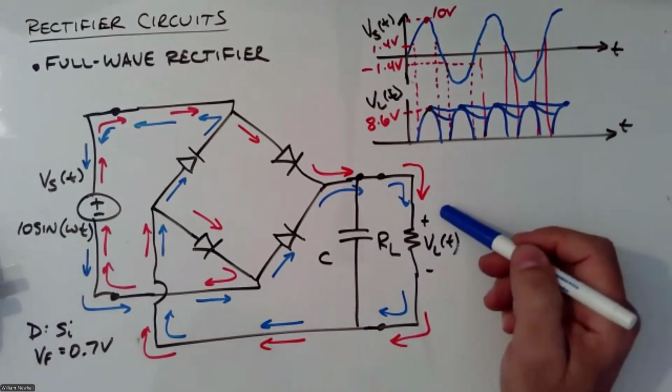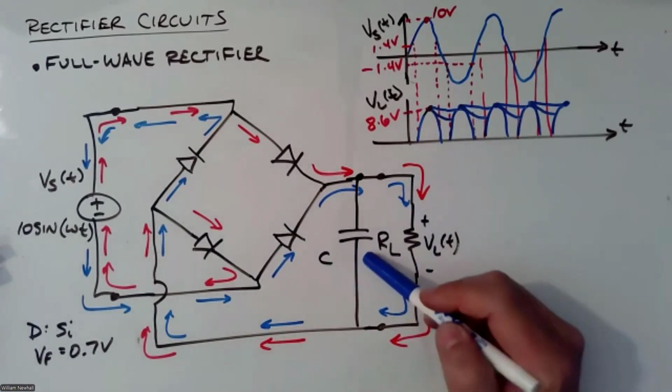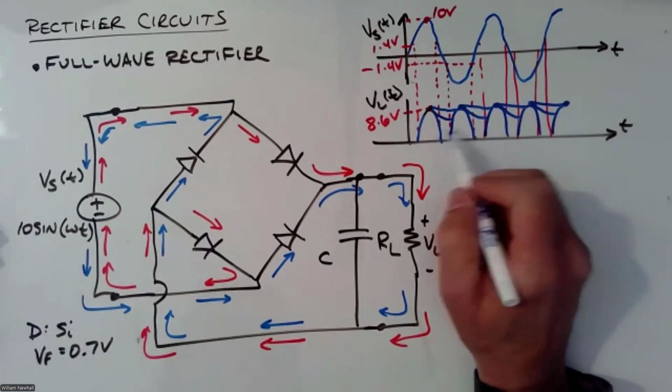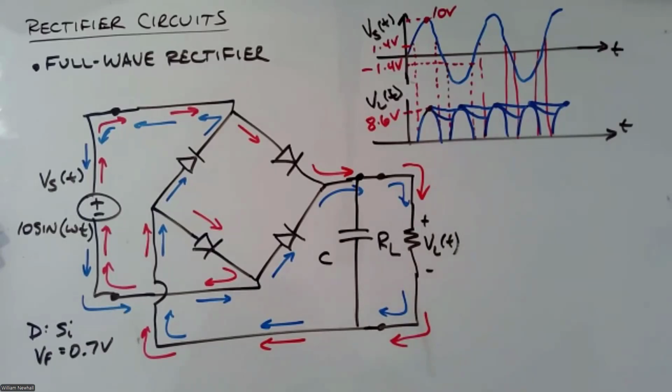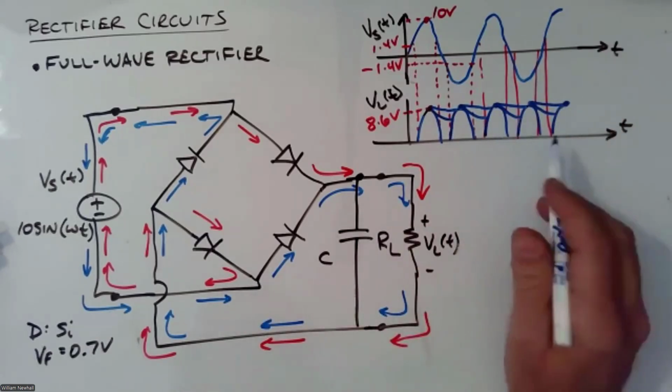All right. So why do this? Why use 4 diodes instead of 1 diode? Well, you can use a smaller capacitor, because you have a shorter time between the cycles, between the charging half cycles of that capacitor. So you can use a smaller capacitor.